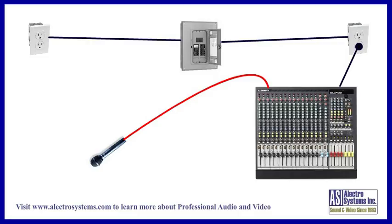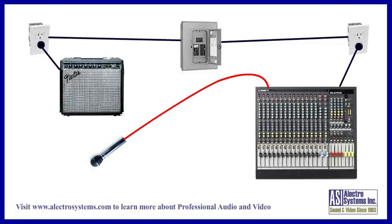If, however, you add another AC-powered device to the sound system, such as a powered floor monitor or guitar amplifier, you now may have to deal with a ground loop. Let's look at the guitar amplifier situation. Because the amplifier is plugged into a separate AC outlet, its AC ground is now connected to the mixer ground through the audio line interconnecting the two. The voltage difference between the two grounds creates a current flow through the wire, which causes a 60 Hz hum or buzz to be injected into the input of the mixer. To eliminate this problem, you need to break this interconnection of the grounds.